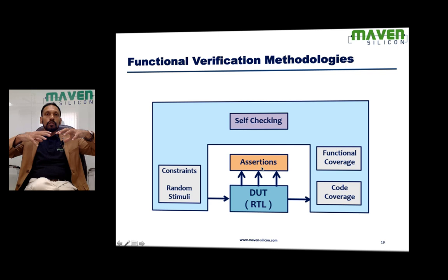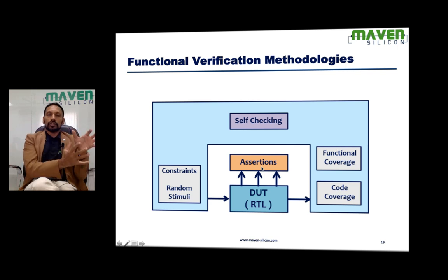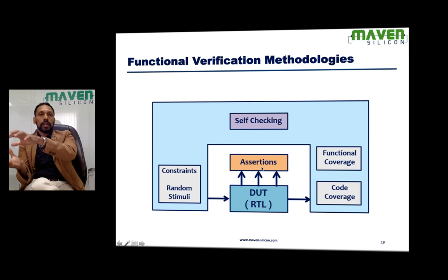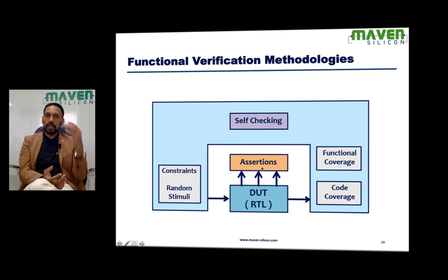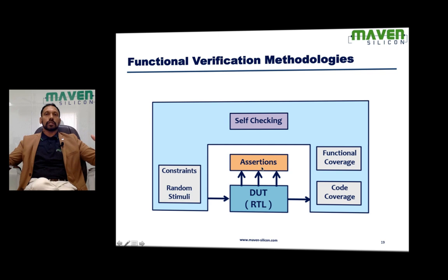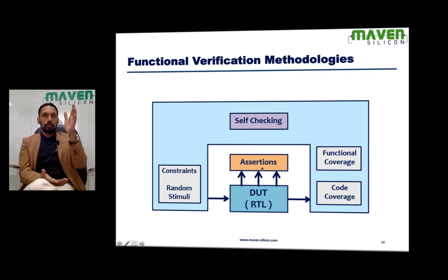This is how we do multiple things like data integrity checking, protocol validation, and coverage-based verification. And we also write different kinds of random test cases to generate different kinds of test scenarios. So we do multiple things, and that gives us confidence during simulation. Yes, we have done multiple things. We fixed almost all kinds of bugs in the design. So during verification sign-off, we look at the coverage report. Also, we look at how many bugs we identified. If we have identified more bugs, obviously the quality of verification is more.